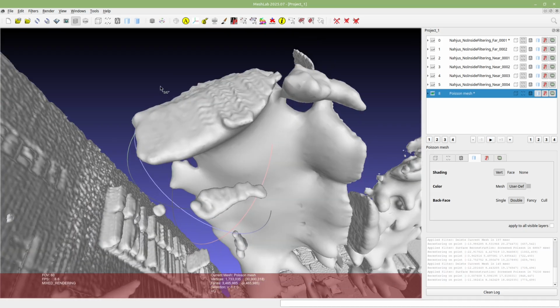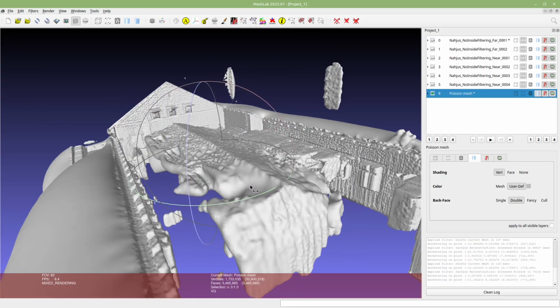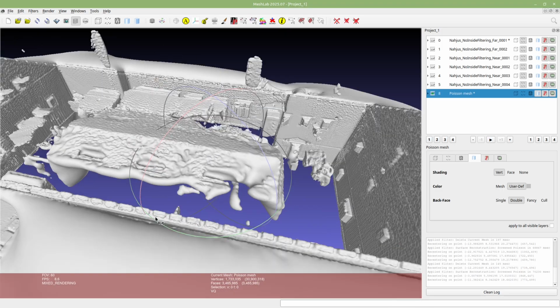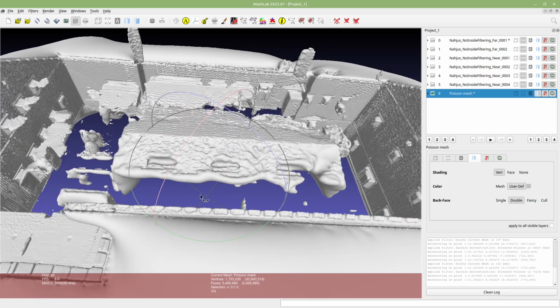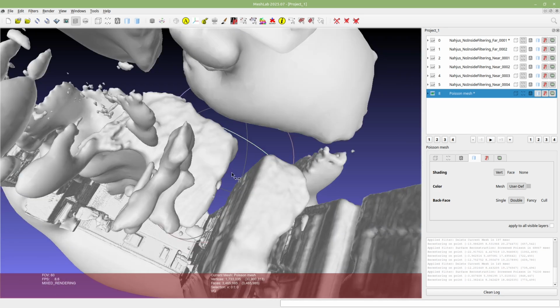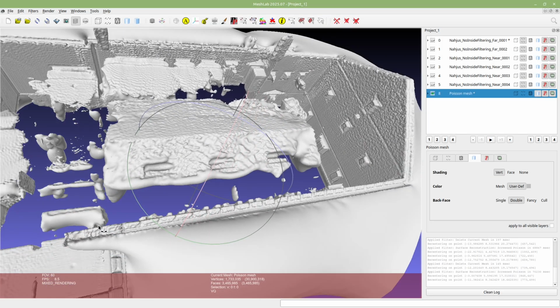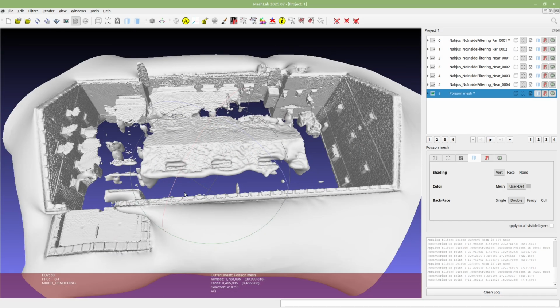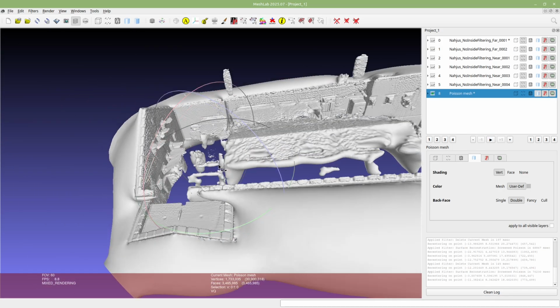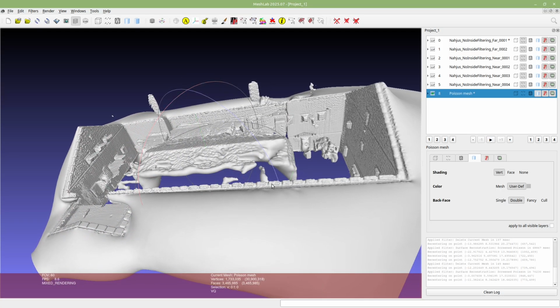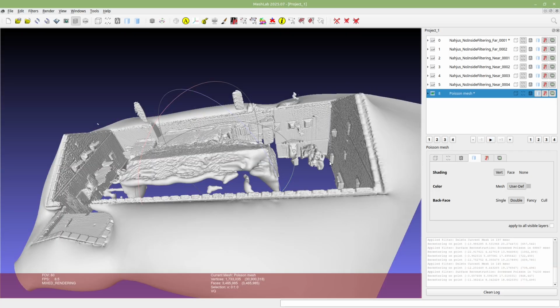And here are some weird blobs inside the building, because they were reconstructed from the points there, not enough to really form any meaningful hall shape here, but the algorithm tries its best. So it's better to filter those points a bit more and add some points to the roof to get a better shape. So let's see that next.